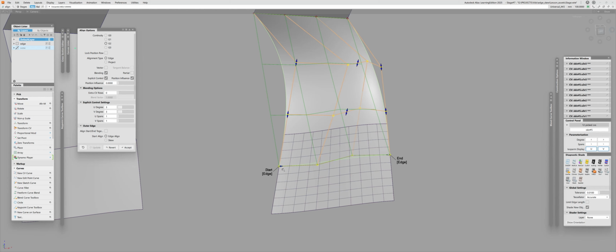If it is not, and it's just somewhere in the middle, on a curved surface which you created somewhere here, for example, then yeah, you are out of luck. It will not behave like the proper edge alignment. It will not be collinear. It will not follow the isoparms. It will not be aligned parametrically. Instead, it will be aligned geometrically using the normalized vector. So what are we going to do with this? How can we overcome these problems?